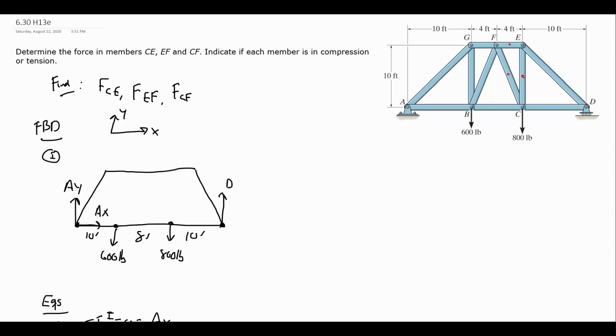So if we take a look at the bridge, how can we make a section cut here? Can we make a cut that goes through all 3 of the members, but only those 3 members, so that we're not making extras? If we try and make a cut like that, it could come in like this, and that's not really going to work. We don't really want to cut back on ourselves, and then we're going through another member anyway.